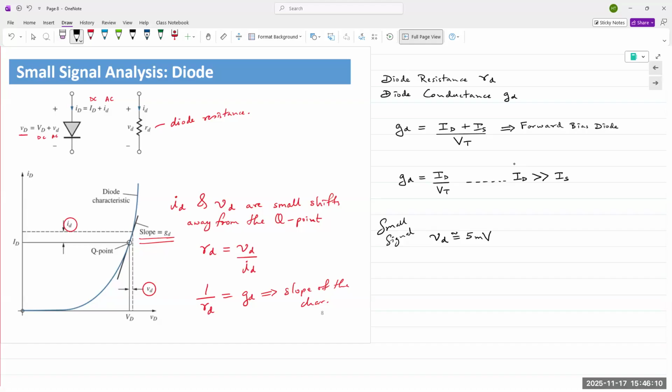Yes, peak to peak value that is being given, approximately equal to 5 millivolts. So if the input is that small, then we can treat it as a kind of a linear device and we can apply linear techniques to that analysis. So all of semiconductor analysis is approximations and assumptions in order to simplify, because no single model can suffice for all environmental conditions or all circuit conditions. We have to have different models for everything.